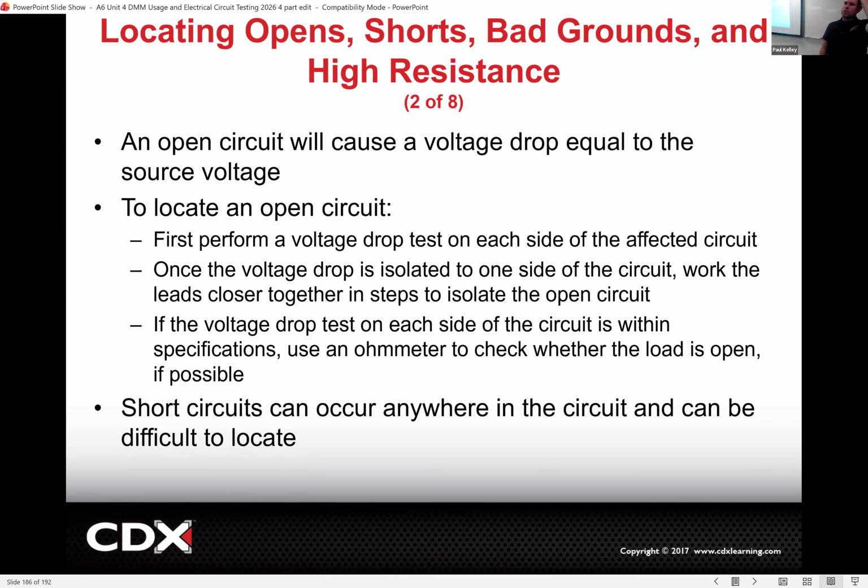So we'd have to troubleshoot the short, and that was the thing we covered last time: you can use the bulb and disconnect things until the bulb goes out, and that shows you've taken away the short to ground. What's the difference between the short and the bypass, though?